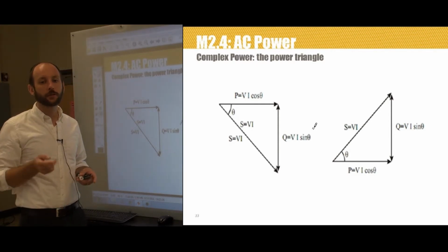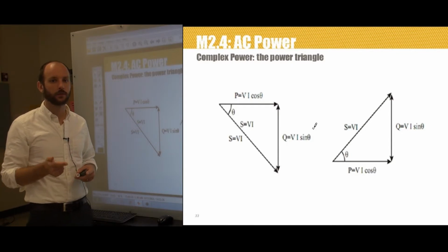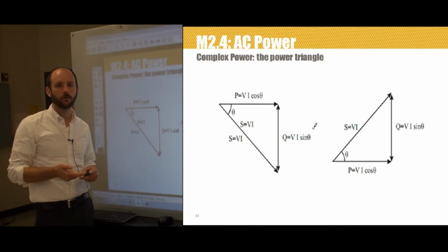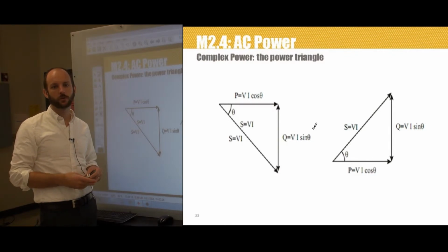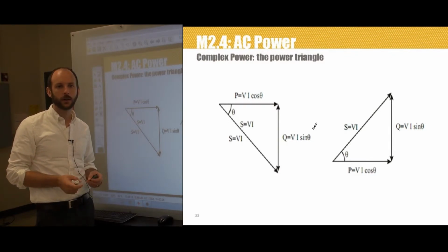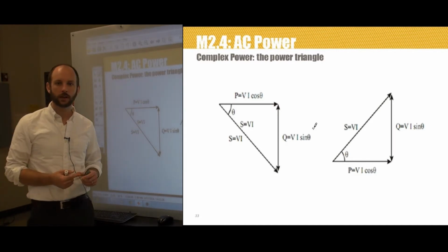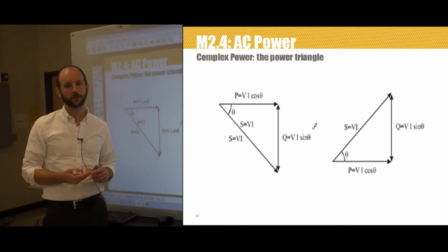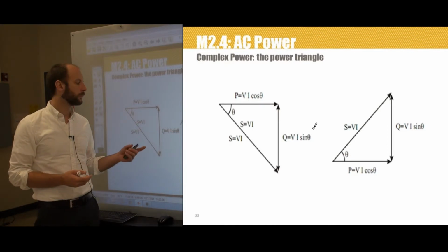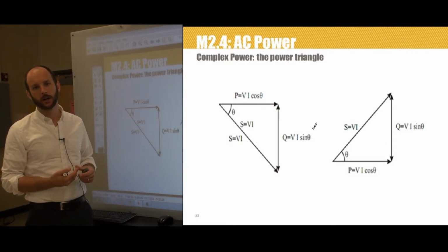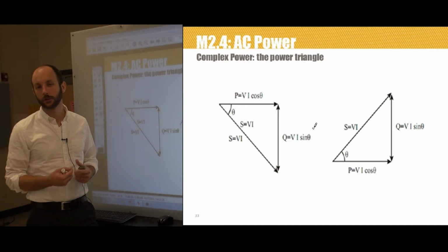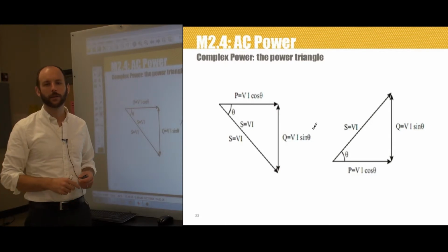power. If the utility fails to balance the VAR requirements of the load, the voltage and the frequency in the circuit will be changed to enforce the law of conservation of energy, and failure to maintain a reactive power balance will typically manifest as a voltage variation on the system. In contrast, failure to provide real power typically manifests as a frequency variation. We'll learn about that in generators.